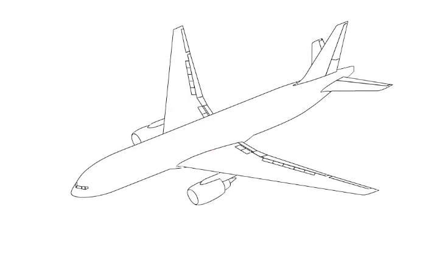Because of the high minimum speed of jet transport aircraft, even the fitment of trailing edge flaps does not reduce the takeoff and landing run to acceptable values. For this reason, in addition to the most efficient trailing edge flaps, jet transport aircraft must also be fitted with leading edge flaps. The next lesson will examine leading edge flaps in detail, plus the operational details of high lift devices.